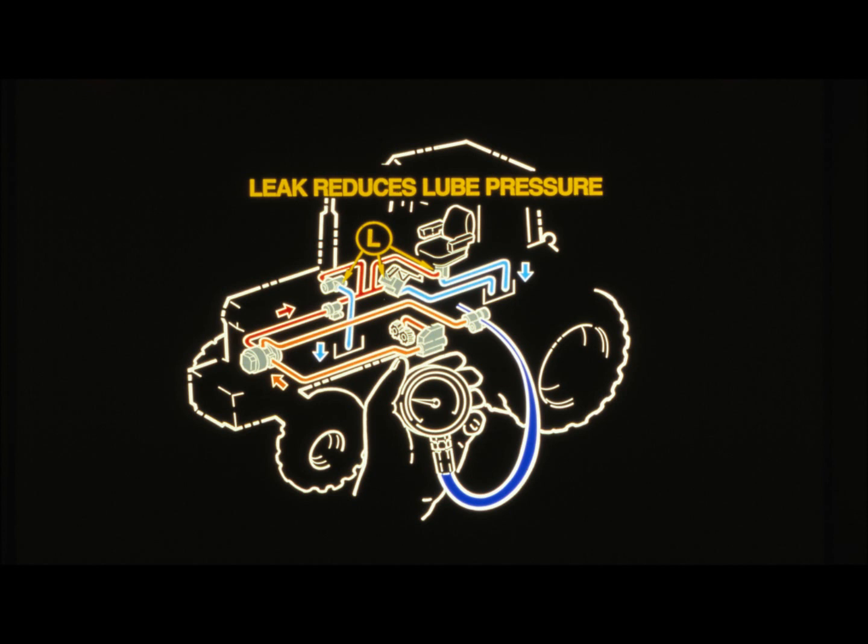Normally, very little oil flows to the diff lock, brake, and seat valves as they operate. A leak in one of these control valves will increase oil flow substantially and reduce lube oil pressure. An unacceptable leak to sump will change lube pressure by more than 2 psi.